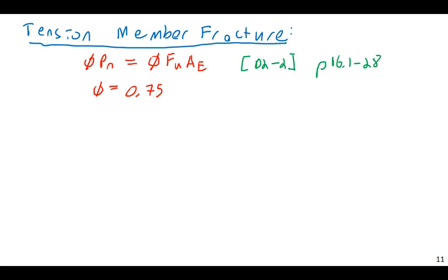Yes, it's bad if you have a lot of deformation and maybe people are bothered by it, or there's enough deformation that you get big cracks in your brickwork. That's still considered a failure, but at least something's not falling on somebody's head. So that is why we have a lower, more critical resistance factor for fracture. It is a much more dangerous failure mode.